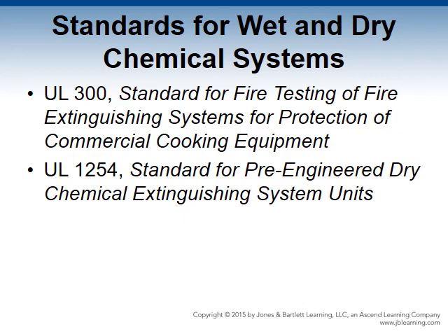Both UL 300 and UL 1254 have specific requirements for pre-engineered wet and dry chemical extinguishing systems, as referenced in NFPA 17 and 17A. 17A requires that pre-engineered dry chemical systems meet UL 1254 or an equivalent standard.